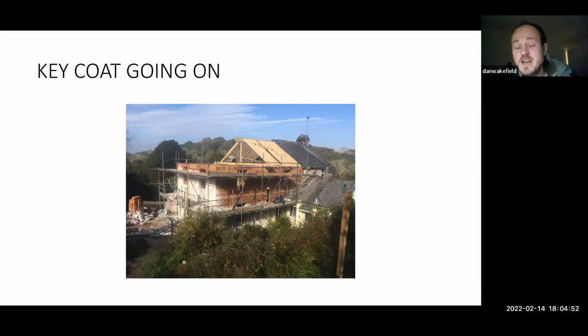One thing I meant to put in, which I forgot, was these 365 blocks are a really natural, nice size to use. They're not too thick. I think we've got a 0.18 U value. So we've managed to get to Passive House with this, but we're in Devon and we're also semi-detached. If you were to go outside the southwest, with any other form factor, you'd really struggle to get to Passive House.